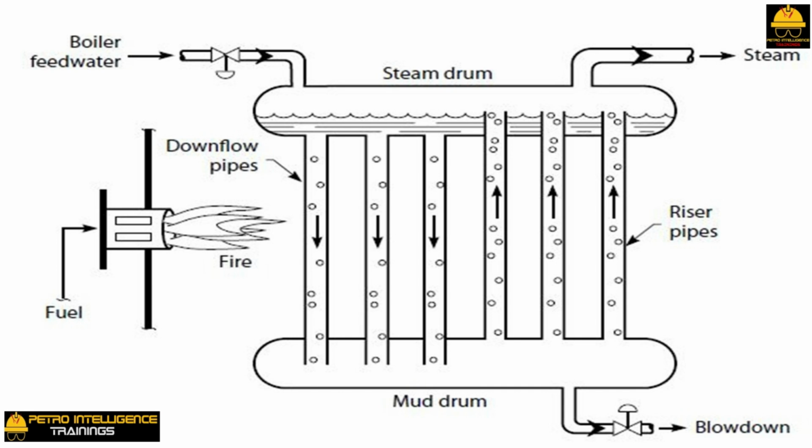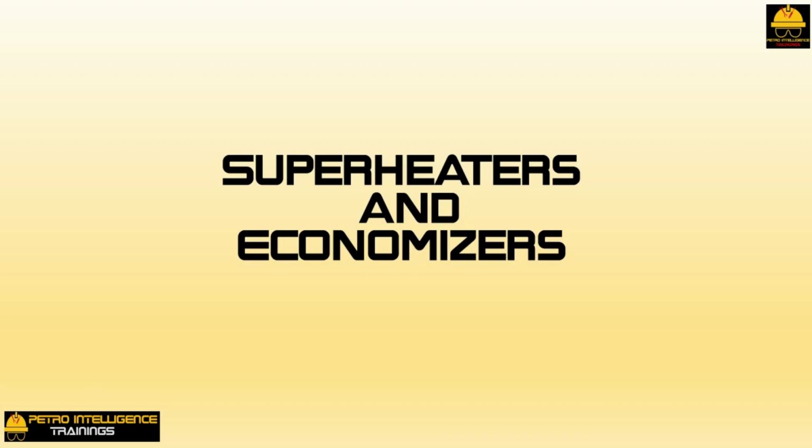This discrepancy causes water carryover with the steam due to high boiling water levels. If we are superheating the steam, then the silicates and other salts in the entrained water will deposit inside the superheater tubes. What I have just described is the leading cause of superheat tube failure. Most of the trouble can be avoided if you understand that the actual level inside the steam drum is higher than the external water indication shows. I have explained this matter in greater detail in the video on waste heat boilers.